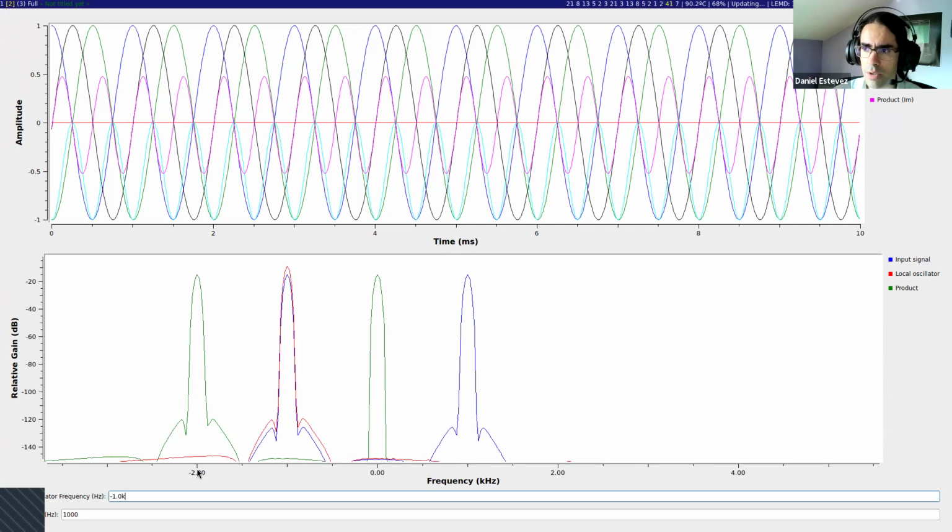It is generating a local oscillator at 95 megahertz, which is complex. And you might tell me these are electrical signals. What's a complex electrical signal? It's actually two separate electrical signals going on different wires that are the real part and imaginary part of this complex signal.